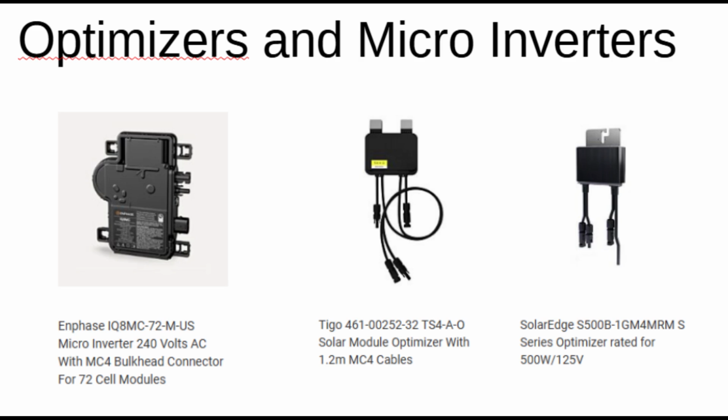Another solution is to put a microinverter with each panel and convert the panel's DC to AC. Each 230 VAC inverter output is then connected in parallel. Enphase is a vendor of microinverters. These devices are located under the solar panels on the roof.